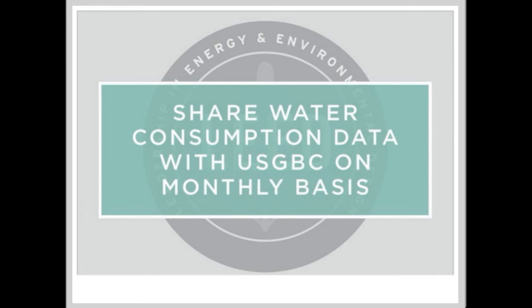Project should begin tracking water consumption during the performance period. Monthly tracking is part of the requirement. Although monthly tracking is required, weekly or daily readings provide quicker information about spikes in consumption and may help identify ways to capture additional savings.